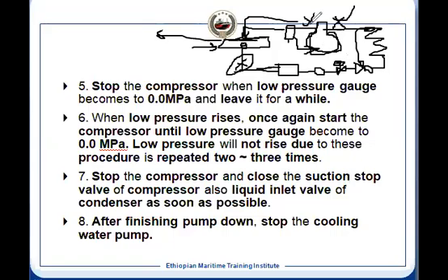Suppose this is the liquid inlet valve, the delivery, you shut. So you have isolated now the condenser from the system, where you have already collected the gases, and it will be in the liquid. Once it is in condensed form, it will change the gas to the liquid because water is flowing, and if you keep the water flowing through that. So once you finish it, then you can stop the cooling water, because now you have isolated these two.